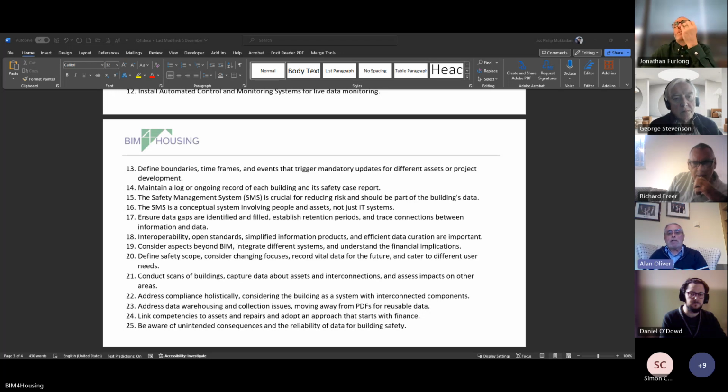The original reference document said you should inspect them 3 ways. You should have a type 1 inspection for brand new doors, a type 2 inspection for existing doors, and a type 3 existing ongoing PPM inspection for doors that have previously been either type 1 or type 2 inspected. Now, the type 1 inspection is very prescriptive, and it's examining the golden thread of information compared to what's actually been installed. So you should ensure that it's very robust.